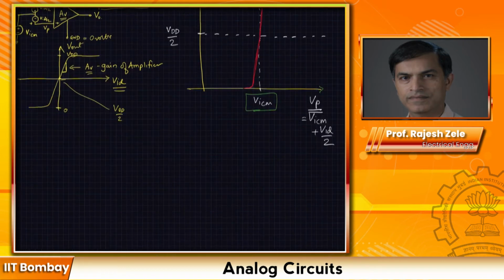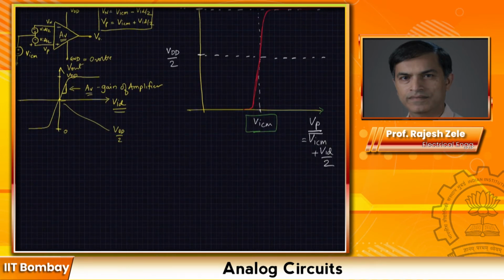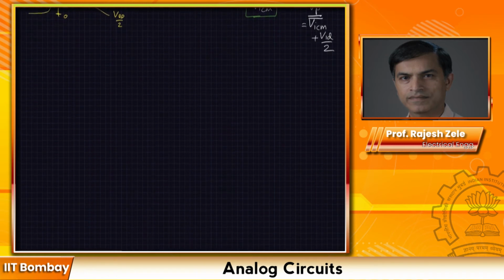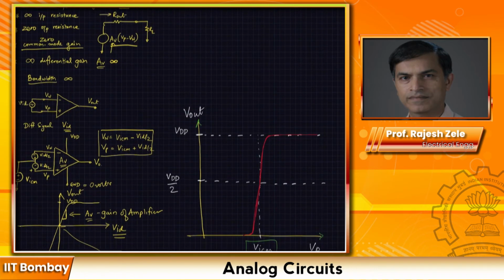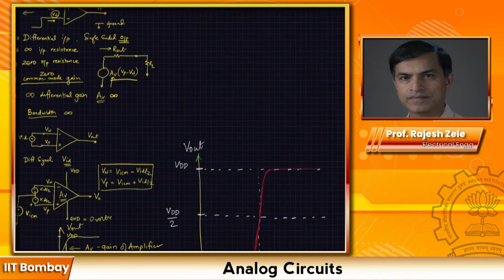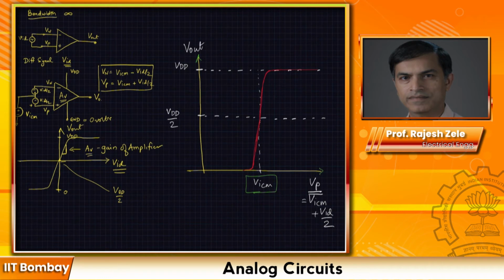All right, so let's discuss the role of the VICM. What does VICM do in this particular case? As I said earlier, we would like to have zero common mode gain, which means that if VICM changes, we don't want the output to get affected. That's the key point I'm trying to make here. So let's say we changed the VICM from VDD by 2 to maybe 3 VDD by 4, something like that.